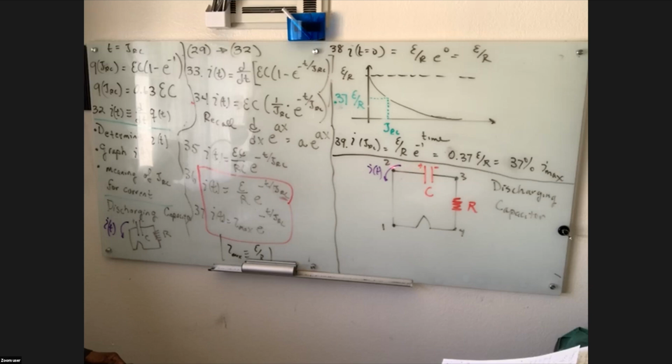So this charge will bleed off, or the capacitor pushes current back around the opposite direction, until it dissipates through the resistor. It heats the resistor up, but the capacitor is acting like a battery without being one. It doesn't have any chemical energy, so it can't replenish its voltage as it dissipates. So the current discharges, and then it just dies down to zero after a certain amount of time.